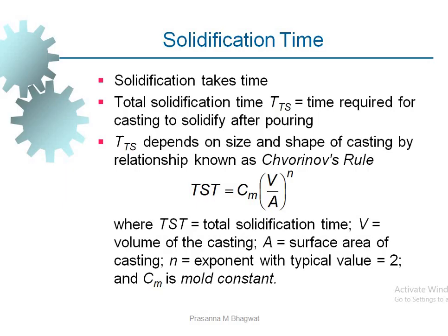So to find out the solidification time, what is the solidification time? The time from pouring to the end of the solidification is called the solidification time. So solidification time, TST. It depends upon the size and shape of the casting, and is given by one rule by a person called Chvorinov.